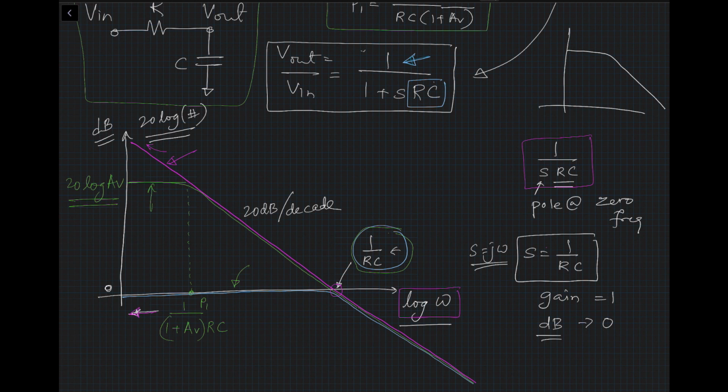So this is in a nutshell how we compare the three particular cases. One is the ideal integrator, then the integrator with the effect of finite gain of the op-amp, and the third thing we plotted a simple RC filter on top on the same lossy integrator. We call this a lossy integrator.